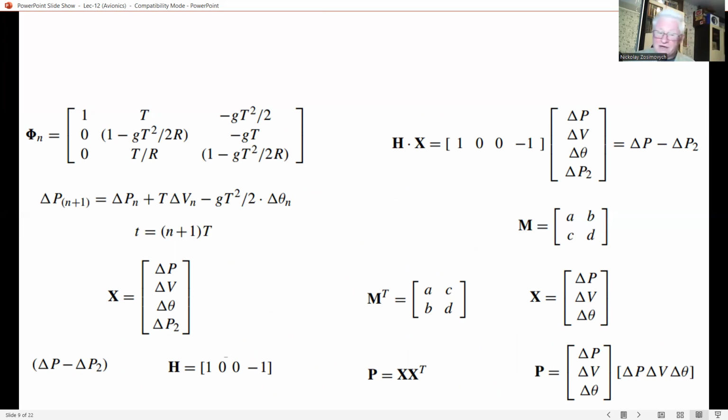As stated earlier, this is a simplified example to illustrate the process of deriving a dynamic error model. A typical Kalman filter INS error model consists of on average 17 or 22 error states.